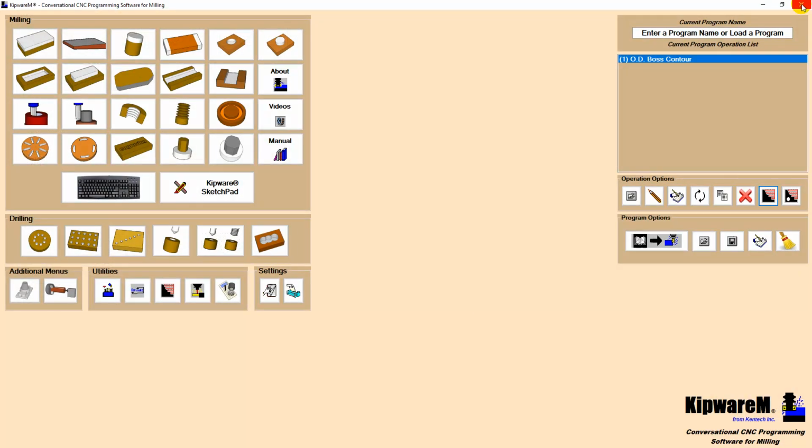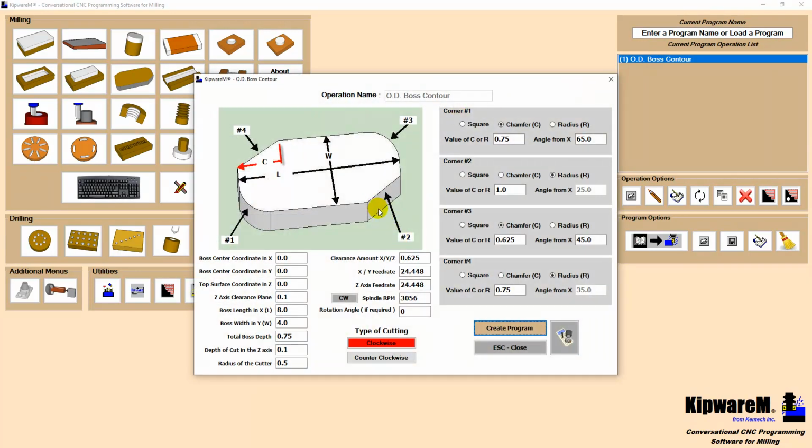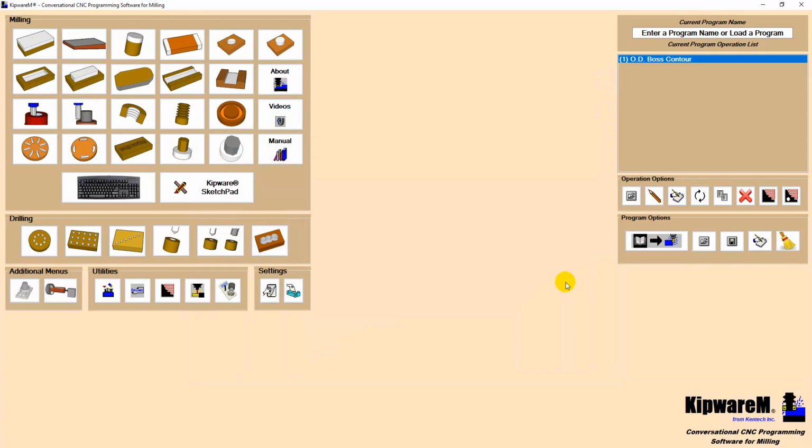As you can see, this is a powerful menu that creates quite complex contours quickly and easily. The machining strategy in this contouring is a plunging strategy that takes depth of cut in Z to create the contour. This cycle could be used just as a finishing cycle if desired, and one of the other standard square or rectangular boss milling cycles could be used as the roughing strategy. These cycles use a stepping in on X and Y as the strategy.